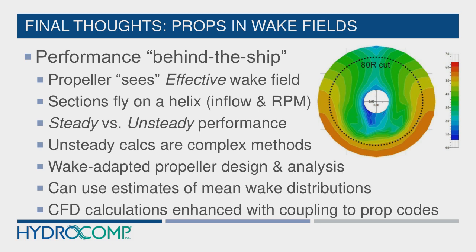Believe me when I tell you, it takes some trial and error to figure out a methodology that is consistent with this, because you have to allow the calculation on the CFD side to get to some level of not convergence but a consistent velocity.